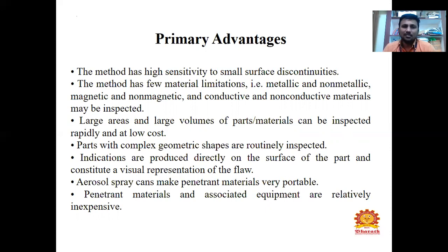Second, the method has few material limitations. For example, metallic and non-metallic, magnetic and non-magnetic, and conductive and non-conductive materials may be inspected, but not porous material. Large areas and large volumes of parts can be inspected rapidly and at low cost.